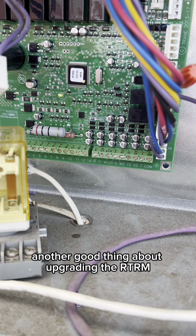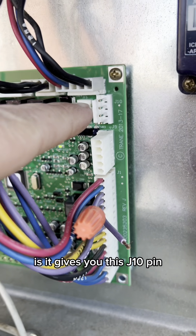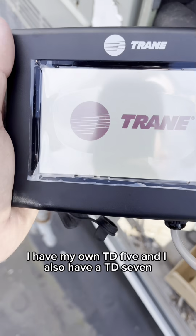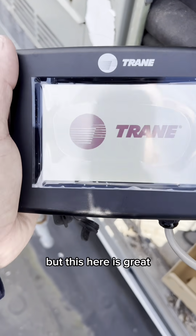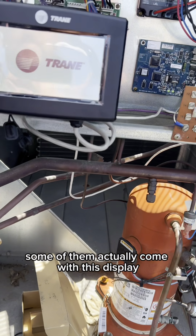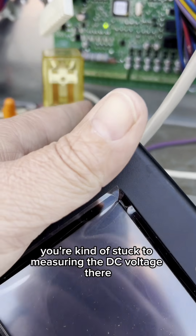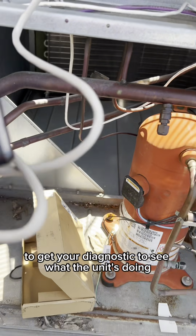Another good thing about upgrading the RTRM to a version 20 and above is it gives you this J10 pin. This J10 pin allows me to use my TD5 display. I have my own TD5 and I also have a TD7, which is used for UC600s that are on air handlers and chillers. But this here is great. If you work on a lot of older Trane units like this, some of them actually come with this display. It's actually an option. If not, and if you don't have a BMS, you're kind of stuck measuring the DC voltage on the J6 pin to get your diagnostic to see what the unit's doing.